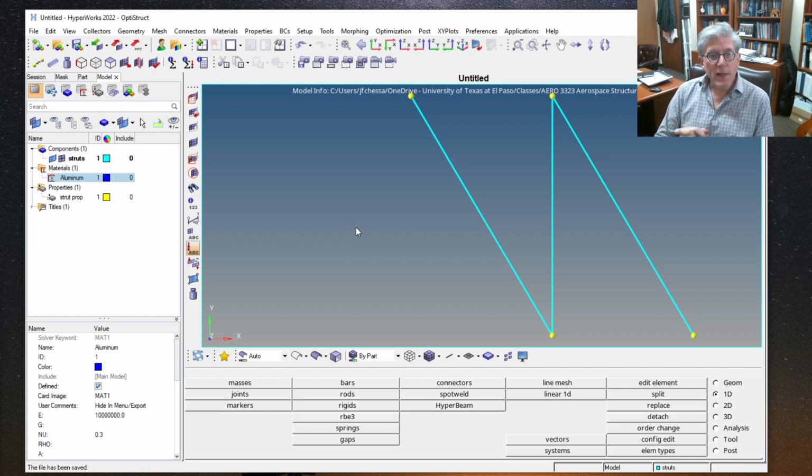Now, the thing that we are missing is I need to put the lift and drag forces at the aerodynamic center of the upper wing. And that's neither this point nor that point. So there's a couple of ways you can do that, but this is the way we're going to do that for most of these things.